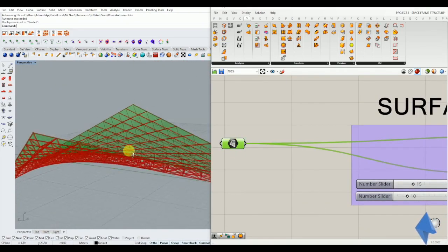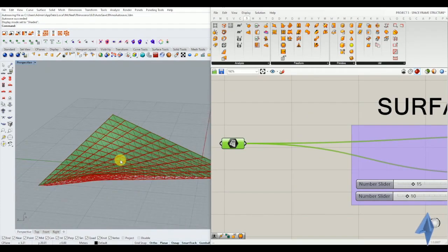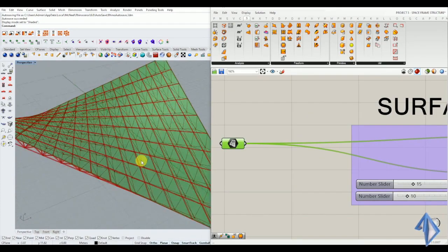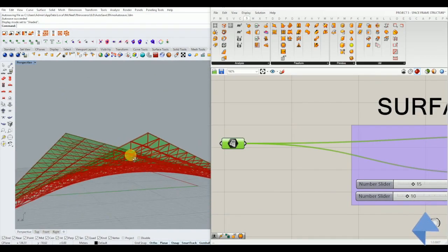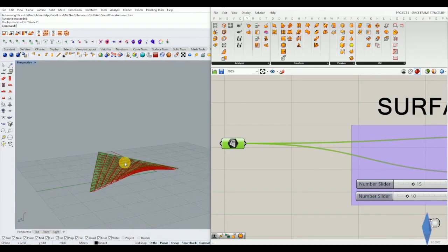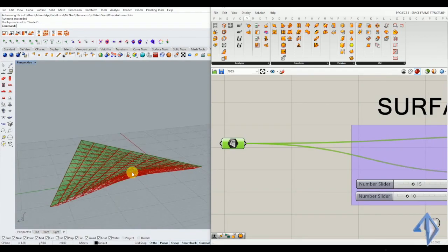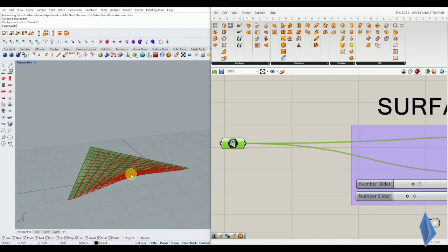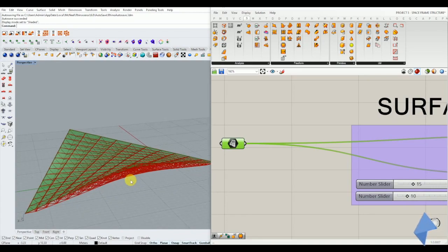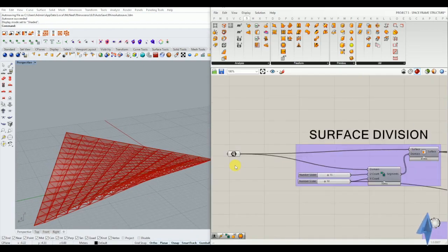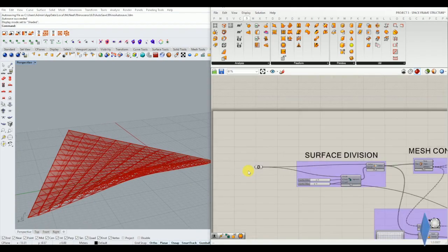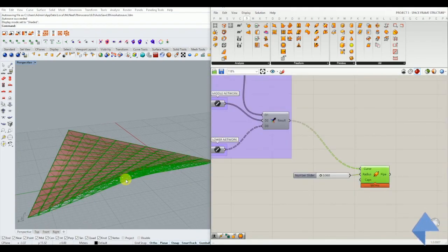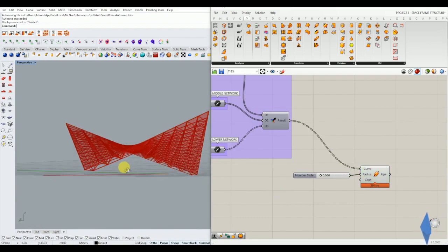This may be a roof structure or an organically created structure which can have a single curve, a double curve. It can be a doubly curved surface, a singly curved surface, that does not matter. What we actually want to achieve over here is the ability to create a space frame structure on any kind of surface, and that space frame structure should be parametrically controllable. So that's what we have done over here using this particular script. As you can see, we input this surface, and as the output we receive the space frame structure that you can see on the screen right now.